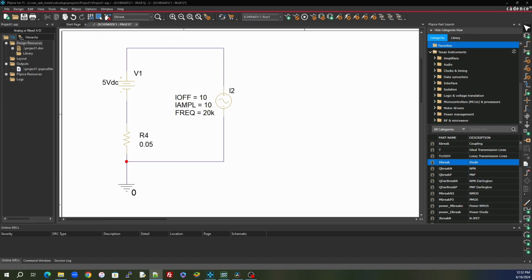LTspice is great if you're using Analog Devices, because you can find all the Analog Devices parts in LTspice, but the way it runs its Spice models, it doesn't necessarily use PSpice outlines exactly. So when you try to download PSpice files from other manufacturers, the import gets really sketchy sometimes, and sometimes you just can't convert it.